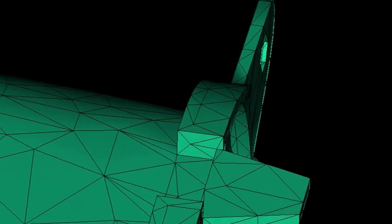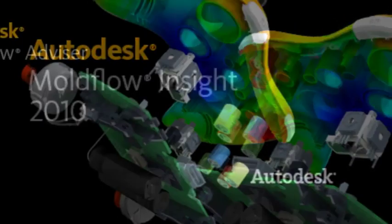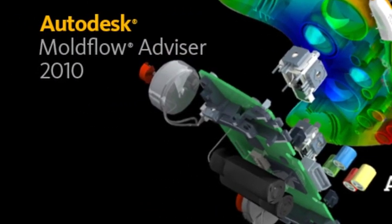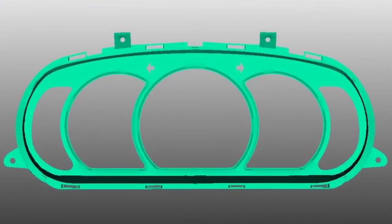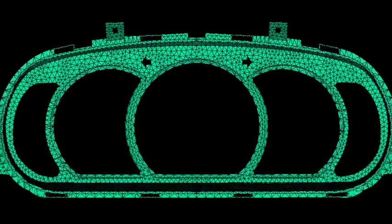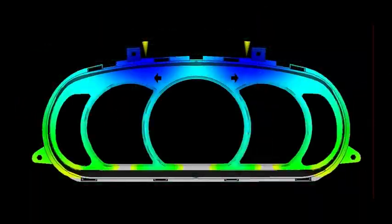And in complex geometries that are solved in injection molding, we can guarantee good mesh resolution through the thickness and an efficient mesh through the other directions of the part, so that we can get our simulation results in a timely manner that people need in today's engineering environment. Autodesk Moldflow includes mesh creation functionality in both Insight and Advisor software so that you can complete the entire analysis from model import through meshing, analysis and export, all within the one software environment.